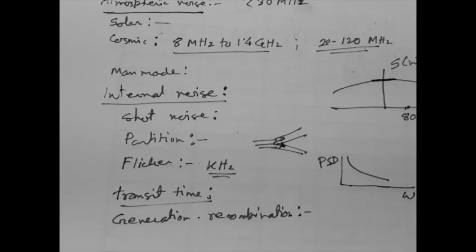The carriers can also recombine with ionized impurity centers on a random basis, either directly or through trapping centers. The overall result is that the conductivity of the semiconductor has a randomly fluctuating component, which gives rise to a noise current when direct current flows through the semiconductor device. The power spectral density of this type of noise is not well understood, but this type of noise is still there.